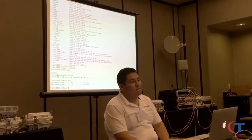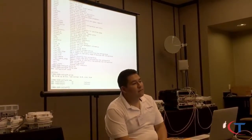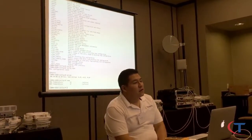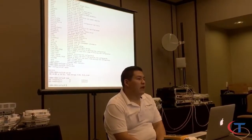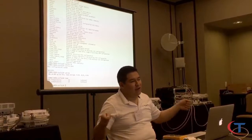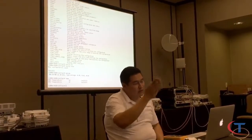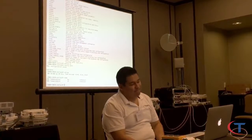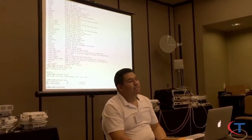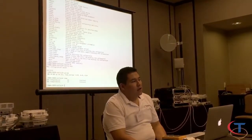Is there anything good? How do you really test it to make sure it's good? Just have a digital voltmeter reading of what it was when you installed it? Yeah, you have to sweep the cable and look at the frequencies coming in return from the cable loss. So there's a special analyzer you connect. There's a transmit frequency, receive frequency, and telemetry as well. It's really just an antenna analyzer, and you just treat the LMR as an antenna. Correct, and then just see how it behaves. Yeah, throw a load on the end of it, maybe.